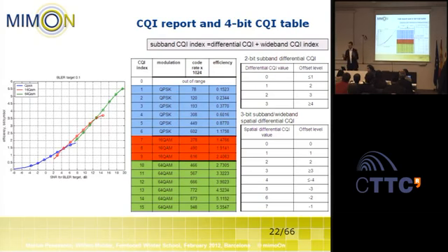But this is known by the user equipment, and the user equipment has this curve. This curve is known at the user equipment, and it also depends on the code block size. Say if I have a long code block, the error correction will work fine. If I have small code words, probably it won't work as well, so I need a larger SNR. So this is highly dependent on the implementation.